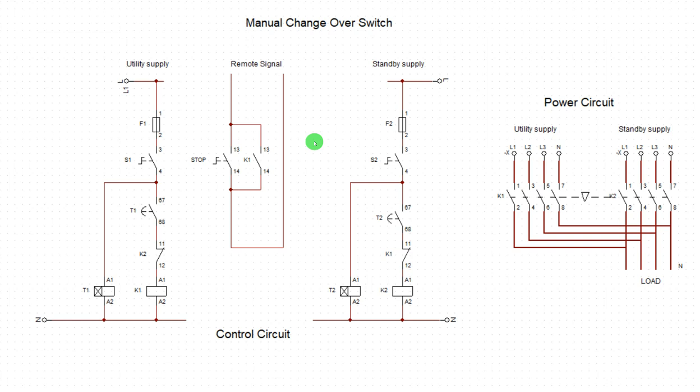Okay, now pay attention please. For the purpose of simulation, we are going to use normally open. Okay, but in reality, it's going to be normally close. The reason is this: the software is still looking at line one as the same source of power. So for the simulation purpose, I'm going to change the contact to normally open.